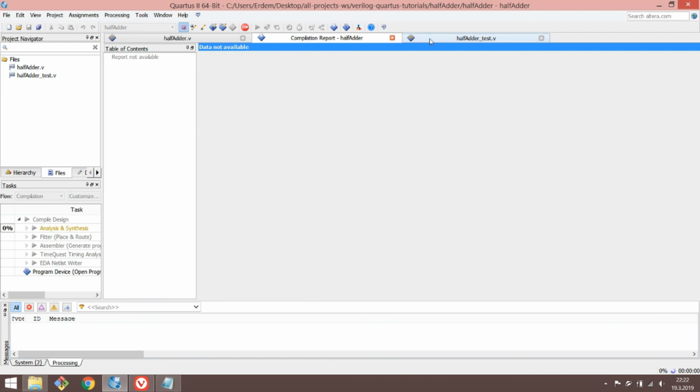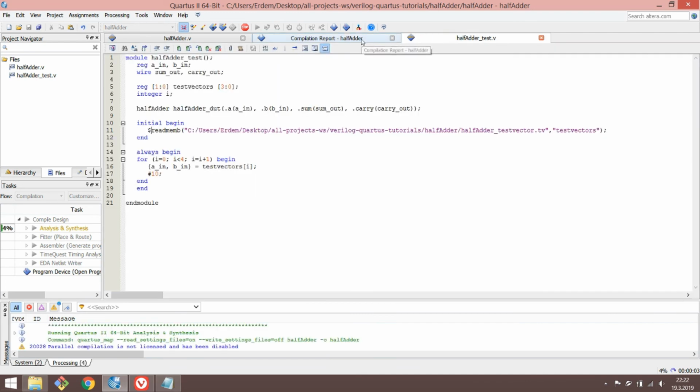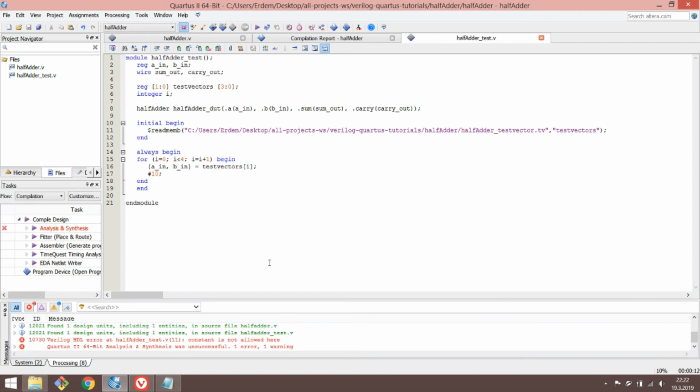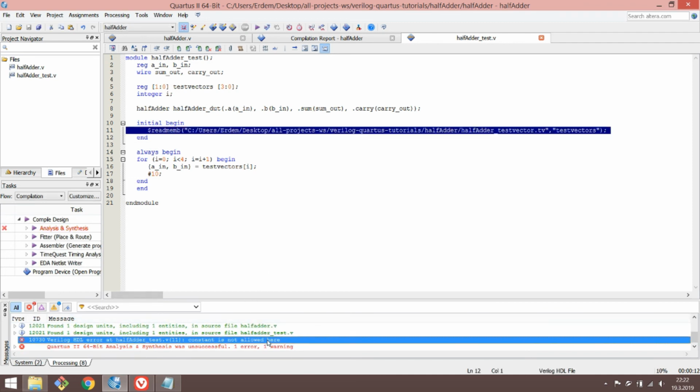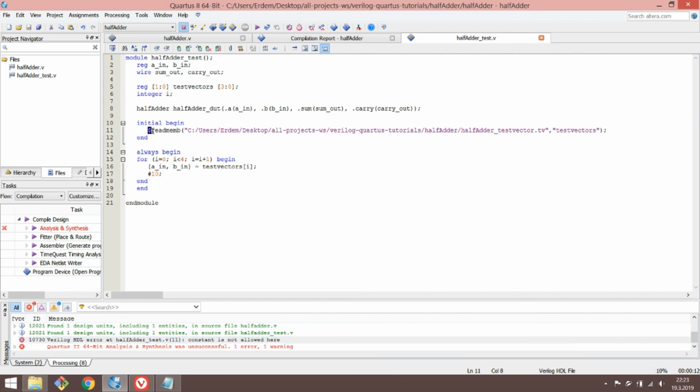So when you change something in your Testbench or module, don't forget to recompile everything to observe your things in simulations. So what we can note here is that at compilation time, the Quartus did not raise any error regarding this dollar sign, and it compiled successfully, but Modelsim just pointed that out.